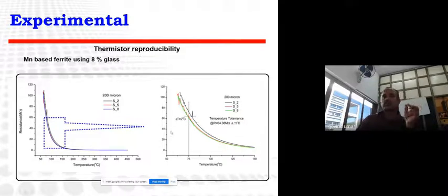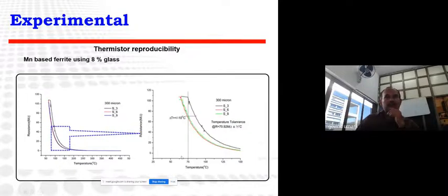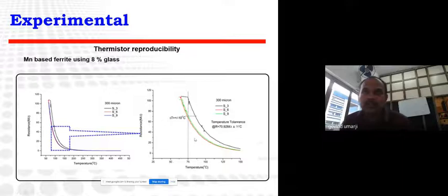That is obviously because we have increased the gap between the two electrodes. In the third case, we used a 300 micron gap, where we observed delta T of around plus minus 10 degrees Celsius, which is not good compared to this. At 75 degrees Celsius, we got 70 mega ohm resistance.